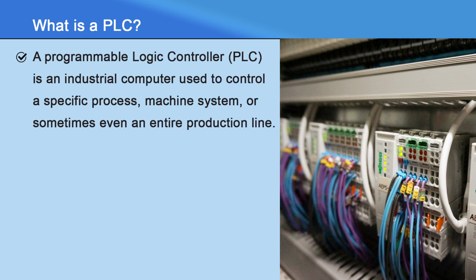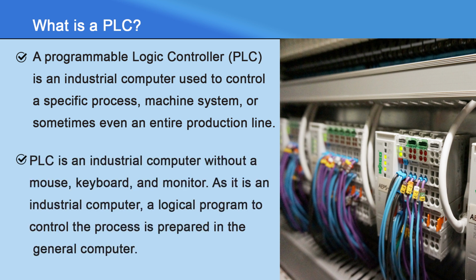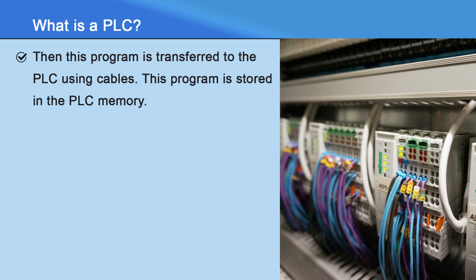PLC stands for Programmable Logic Controller. It is an industrial computer which is used to control a specific process, machine system, or sometimes even an entire production line. PLC is an industrial computer without a mouse, keyboard or a monitor. As it is an industrial computer, a logical program is used to control the process and is prepared in the general computer. This program is then transferred to the PLC using a cable network. Then this transferred program is stored in the PLC memory.